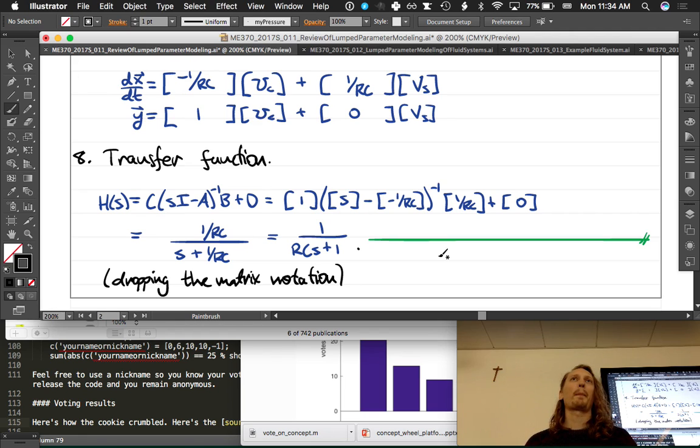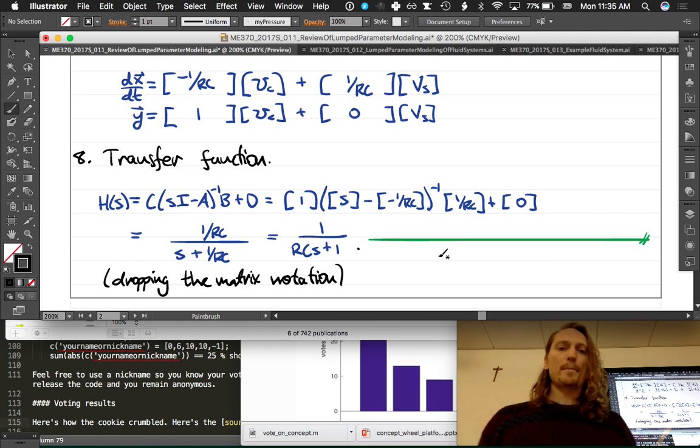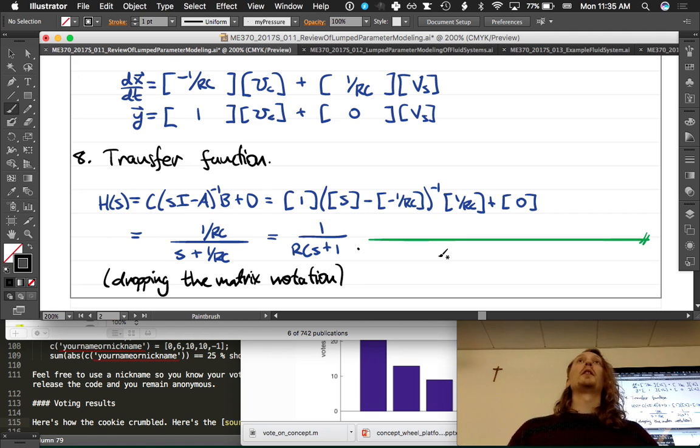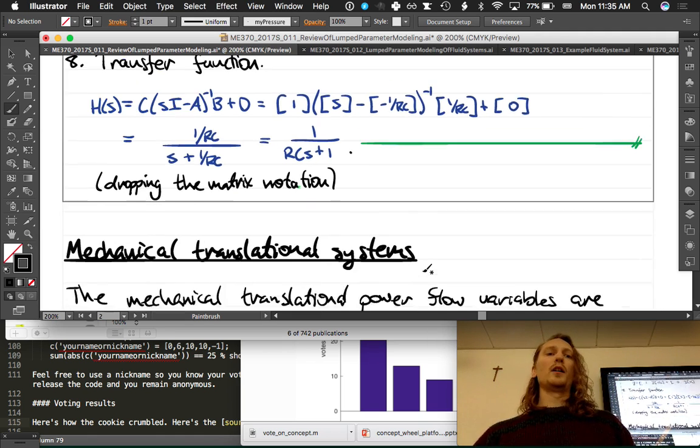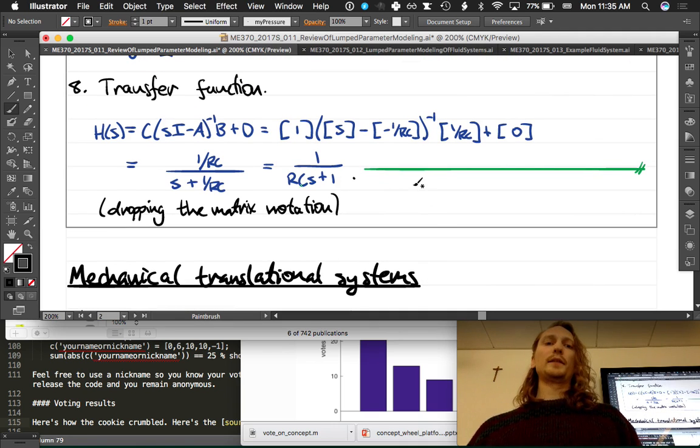So don't you just have like dy over dx and line things up so it's... What you would like, I think, is to find the scalar input-output differential equation from the transfer function. That's the term I was trying to remember. Yeah, let's do it. If we want to know what the IO-ODE is, we know that we have H, which is equal to this, and we know that H is equal to the output over the input.